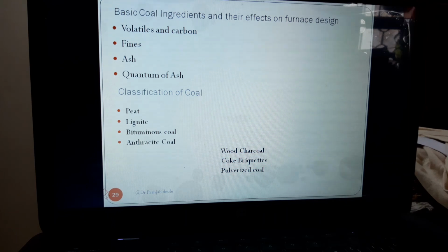It consists of 90 to 95% carbon, small quantities of sulfur, hydrogen, nitrogen and phosphorus. It is a smokeless and clear fuel. Its average calorific value is about 32,500 kilojoule per kg. It is used in steam power plants and blast furnaces and gas producers.